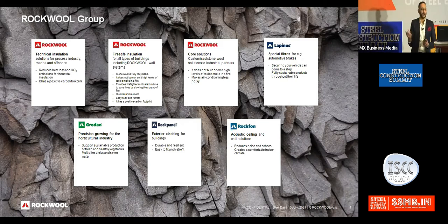So I think, probably just taking the point that Mr. Rathi said in the beginning about steel walls having 2 hours of fire rating. So this is the solution that is actually for that. The sandwich panels which are manufactured using Rockwool as the core solution, they have a 2 hour of fire resistance, backed up by all the certificates and everything.